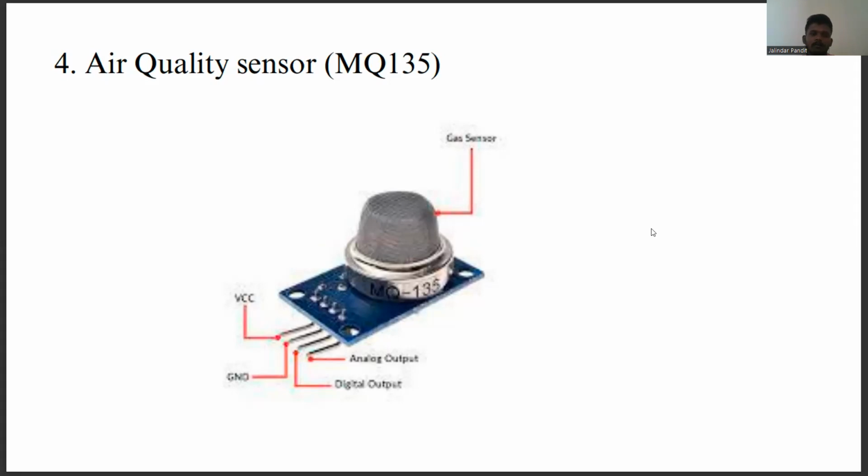Then the MQ135 sensor involves measuring the resistance of the sensing element. When it is exposed to pollution, the resistance changes as the concentration of the pollution increases or decreases, which affects the output voltage and digital signal of the sensor module. The output signal can be read using a microcontroller board such as the Arduino Uno R3 and processed to display the air quality reading on a display such as the 0.96 I2C OLED display.